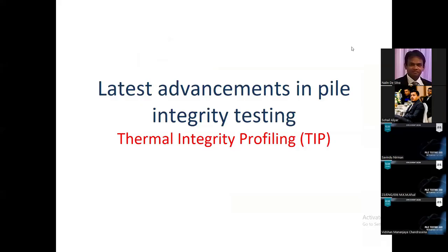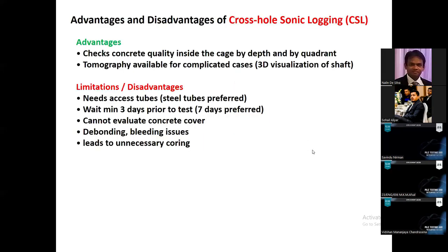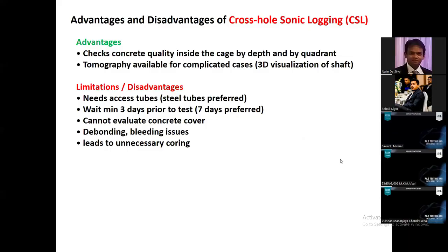Then I would like to discuss a little bit on the latest advancement in pile integrity testing, that is called thermal integrity profiling, the TIP test. It has a lot of advantages. That is why I thought of discussing it in this forum. It is not yet widely available in Sri Lanka. The test is available in Sri Lanka, but it's not very popular. But in countries like the United States, it has become a standard procedure. It is standardized as well.